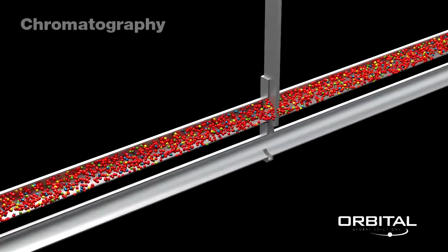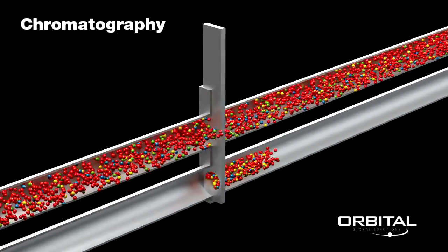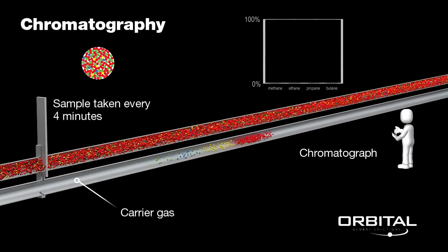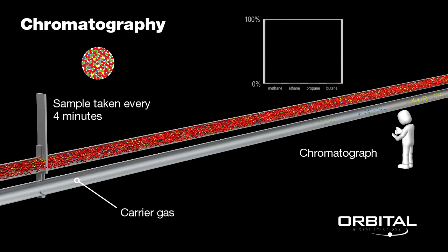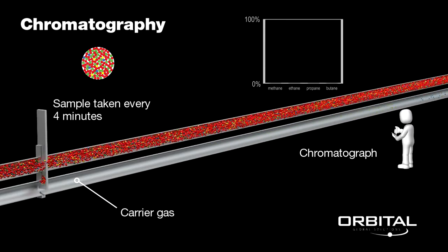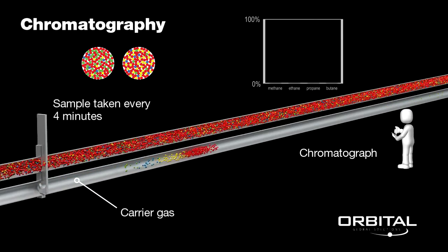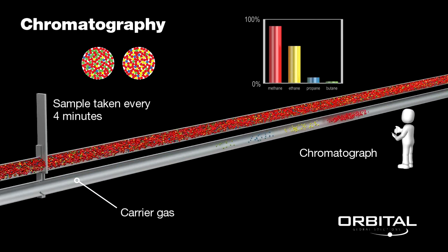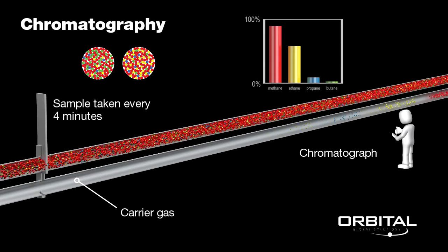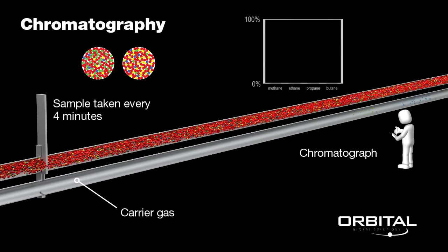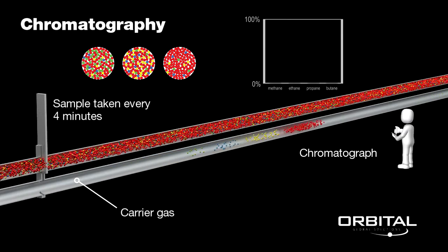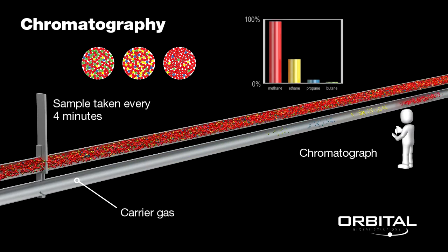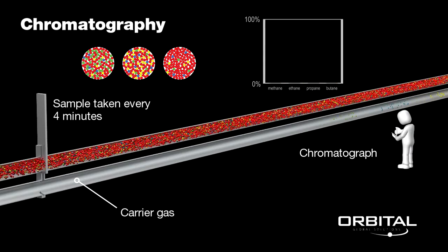Because chromatography uses a tiny part of the sample stream to make the analysis and measurement, this makes chromatography one of the worst possible methods of measurement that could be used for this application. Chromatography literally cuts a tiny slice of the sample from the sample path and injects it into the separation and counting stream. We therefore rely upon this tiny slice to be exactly the same as the entire sample stream.